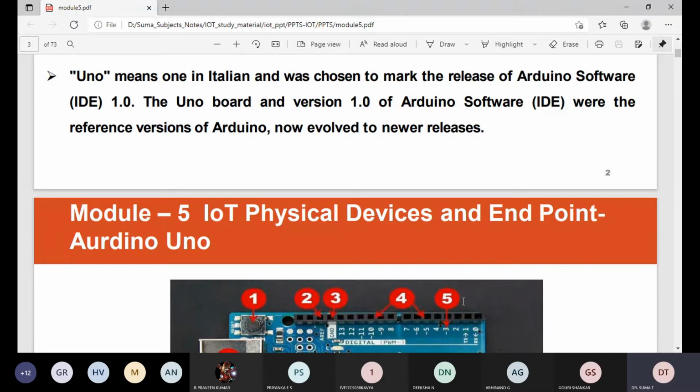Some of the boards from the Arduino family are: Arduino Mega is a big sister of the UNO with more memory and pins, with a different chip, the ATmega2560, useful when your project doesn't fit in an UNO. Okay, Arduino Micro is a bit smaller with an ATmega32U4 chip and can act like a keyboard or mouse, which does this task with native USB. It's slim with download pins which can be plugged into the breadboard.